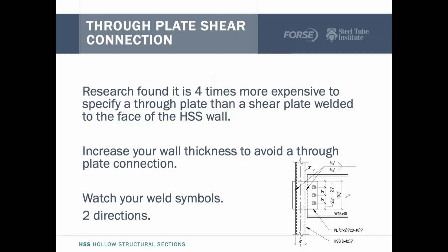I'm not joking, I pulled this detail and redrew it so that nobody could tell where it came from, but I pulled this drawing from a fabricator that sent me their job, and you can see that we've actually got this specified as our typical connection. We've got through plates going in 2 different directions. So the fabricator literally has to cut the tube in half to be able to fit this kind of crucifix